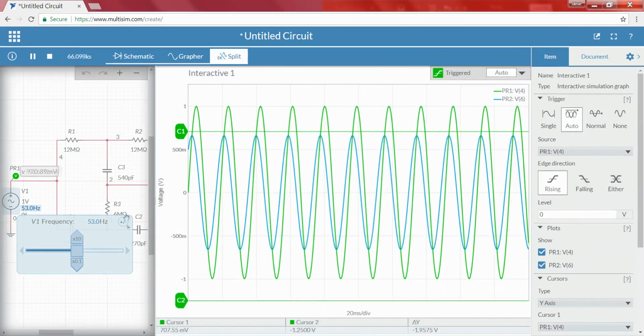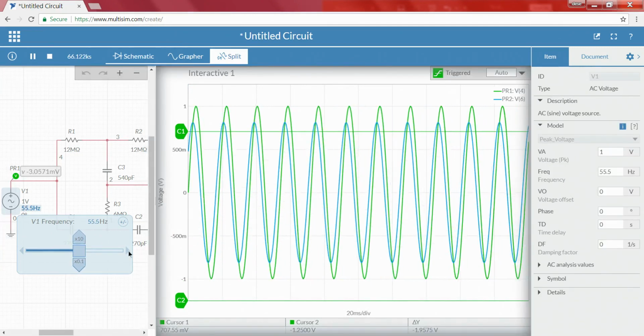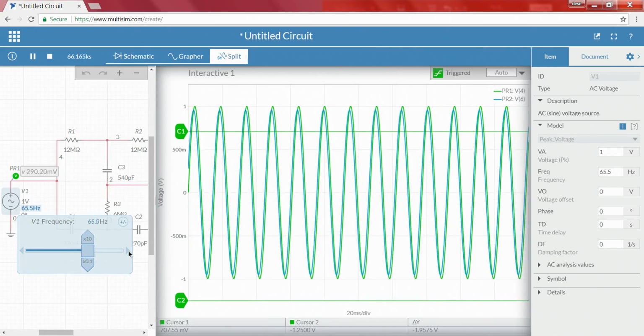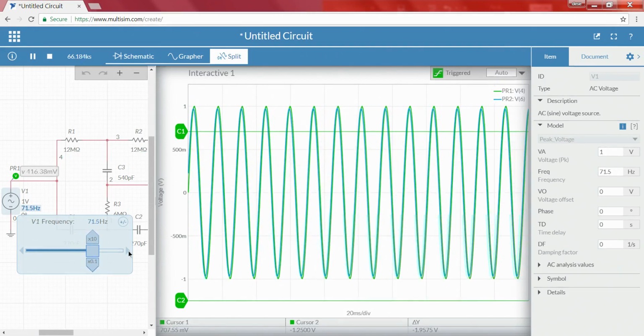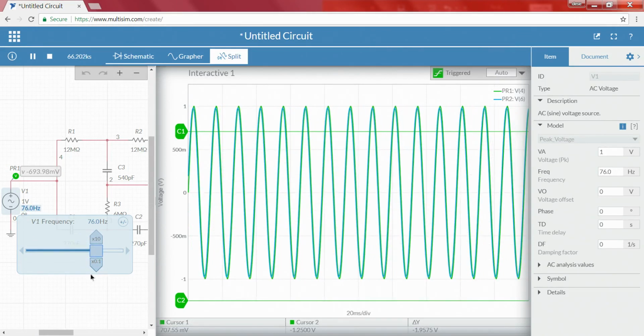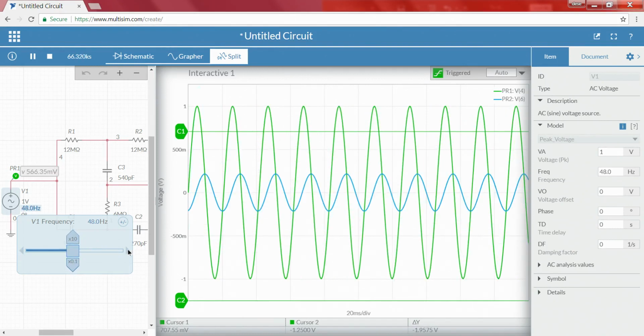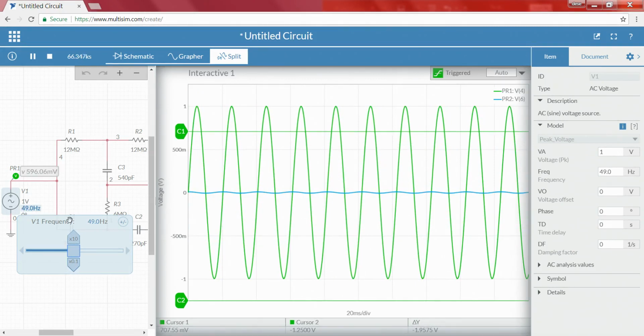Forget about C2, right. But as the frequency is greater than the value, again it follows the input, right. So this we can clearly understand, whether the filter that we have designed can cut off very close to the 50 hertz frequency or not, right.